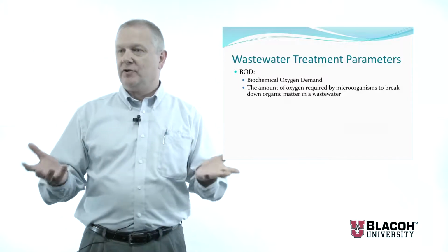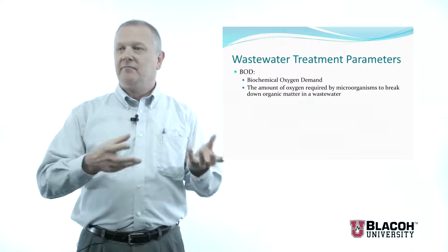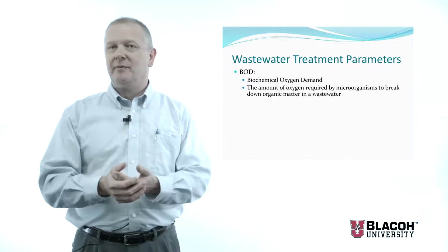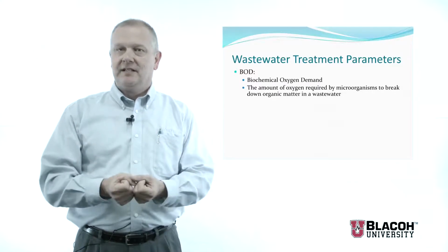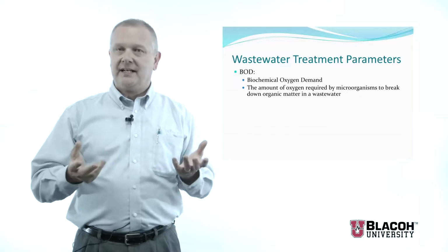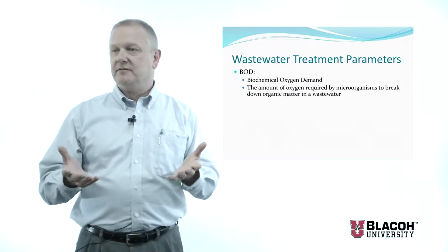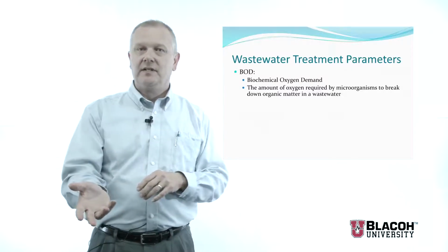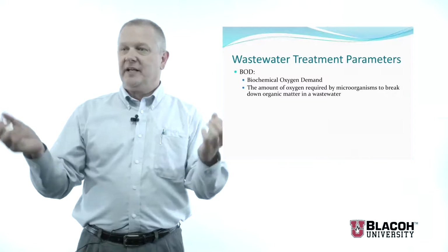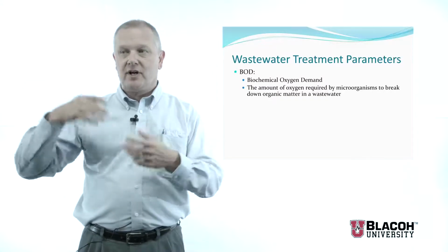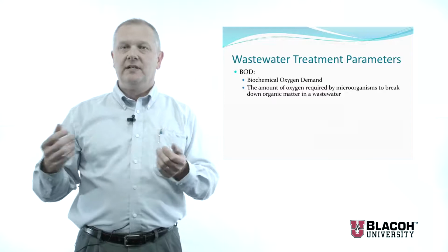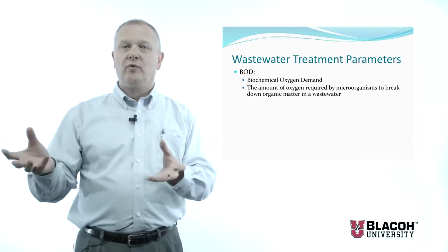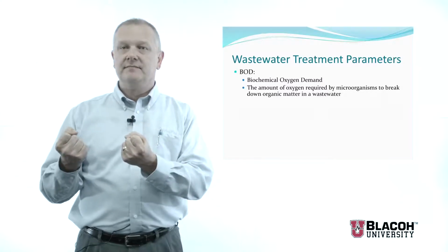The microorganisms in the natural environment will do that. They will feed on a dead animal or any waste, organic matter in the environment. Bacteria break those down, and these bacteria need oxygen to live. If you put some waste material into a stream, for example, and the microorganisms begin to feed on that, and they use oxygen as they do so, they respire like we do, they will grow and multiply. And if there's enough waste there, they will grow and multiply to the point where they suck all of the oxygen out of the water.